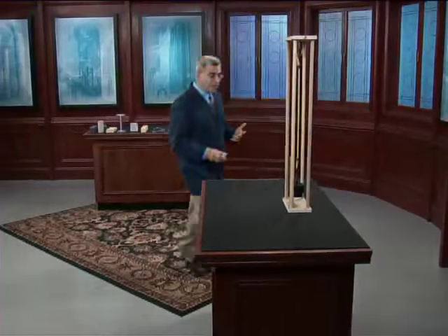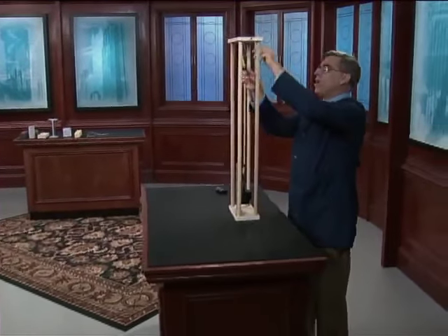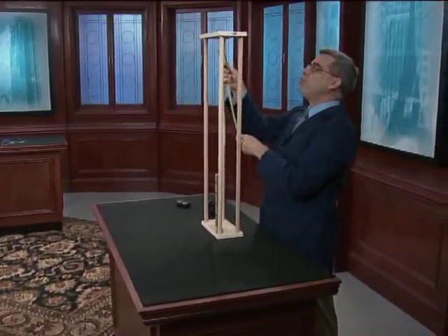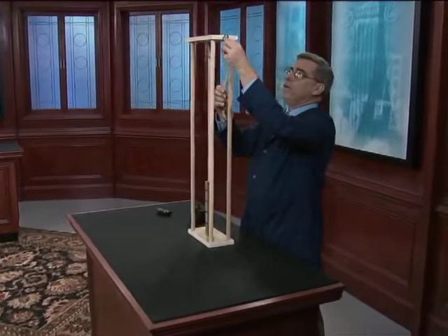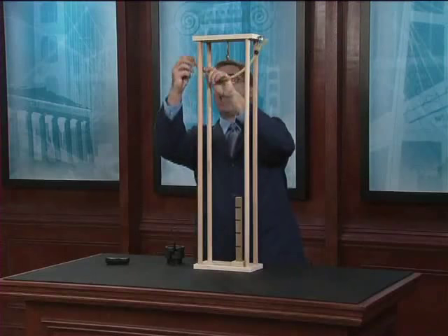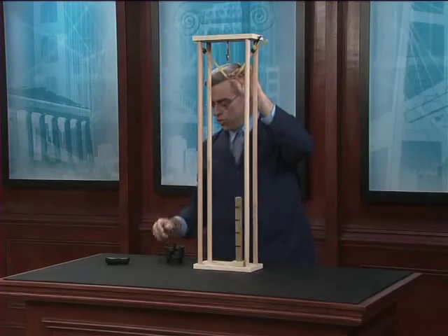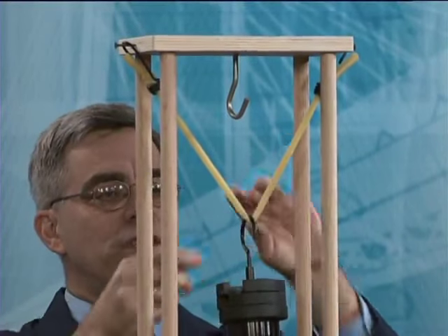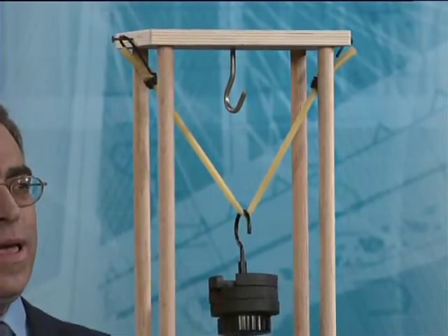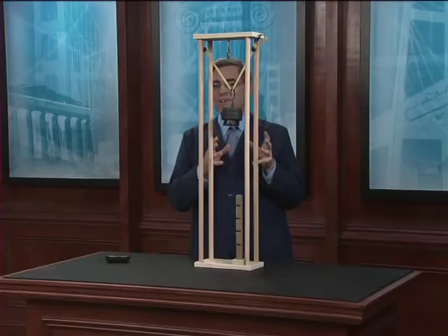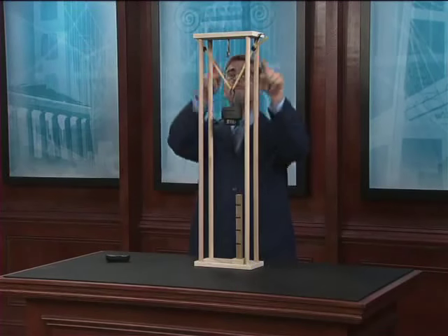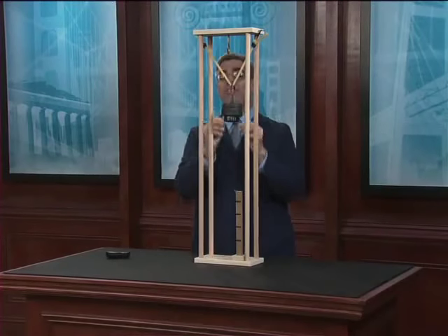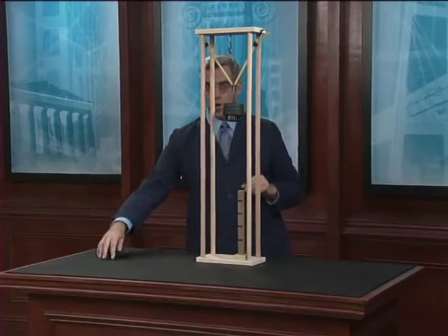For example, if I just reconfigure this experimental setup, that is, if I take the load off for a moment, and rather than having the load suspended from a single wire in one uniaxial test setup, suppose the load is suspended from two wires, which are oriented such that they form an angle. Now, in this circumstance, there is not one internal force, but two different internal forces, and both of them will turn out to be substantially different from the externally applied load.